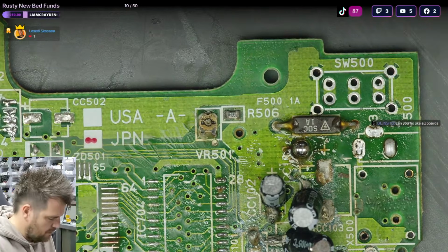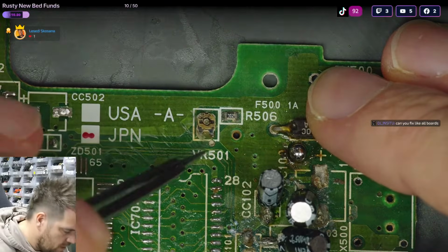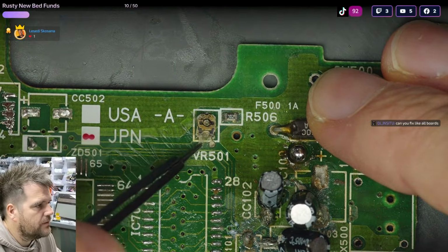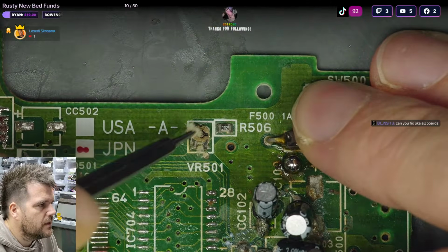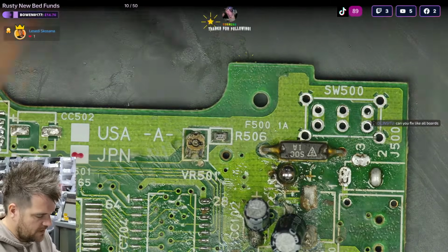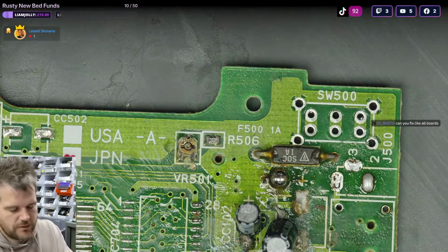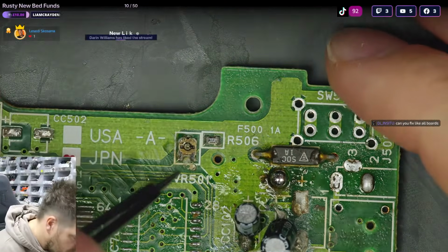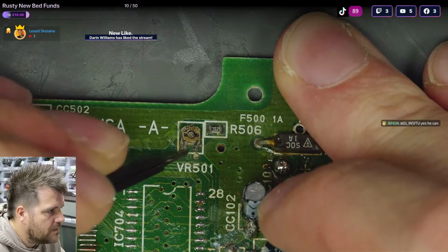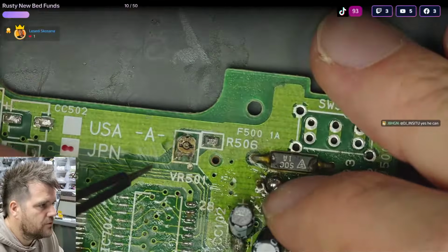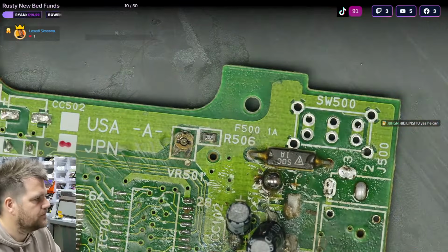Okay, let's do this pot then, this little potentiometer. This is just similar to that volume wheel that we melted yesterday. This is basically an equivalent thing, a 3-pin. So just like the wheel, you'd have a resistance over here, a little carbon pad inside, and this arm would swipe in the middle. So it's exactly the same as that wheel that I showed you yesterday, just in a baby package. And they're always the same pinout, so you don't even need to bother with detecting pinouts or making notes. These little pots are always the same. The outer two legs are the overall, and the middle pin spins around.